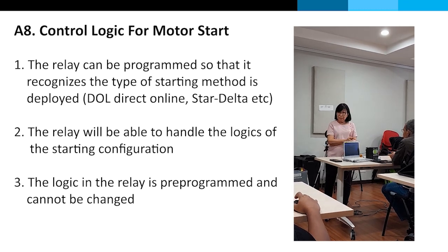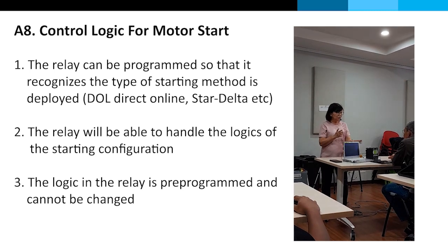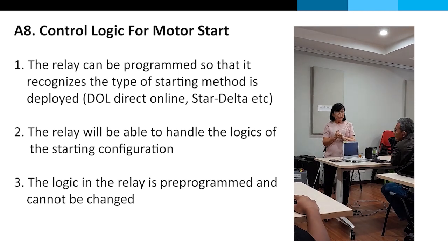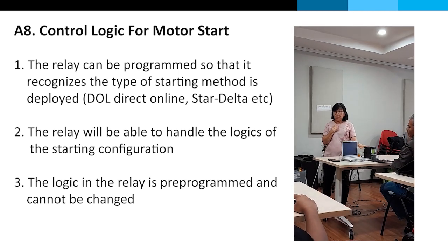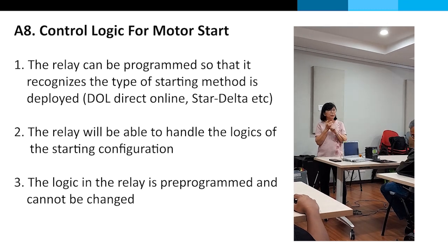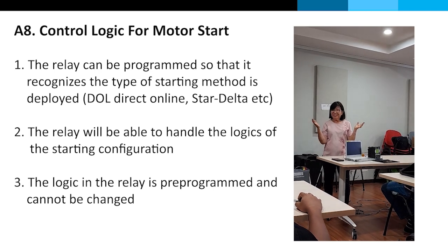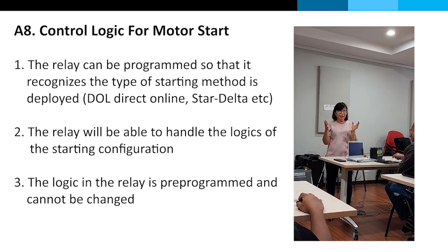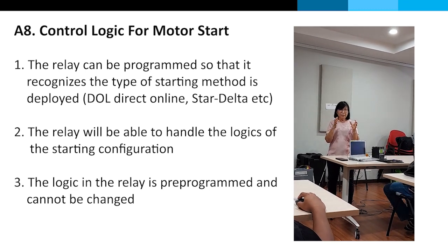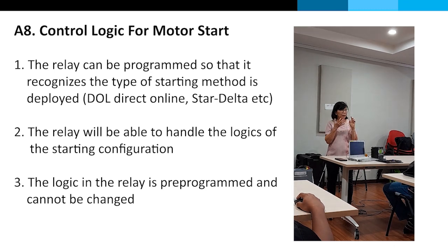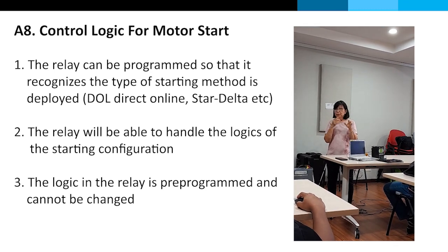So there is this function in this relay, but I don't think you'll be using it. Petronas uses it purely for protection saja. Sebab itu, when you program this relay, you have to put in what kind of start. So for you, it will be no starter. No starter. So if there's no starter, then you have to interpret the BI, the binary input, and the binary output differently. So we will tell you some of these things.